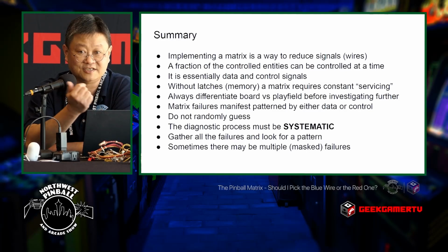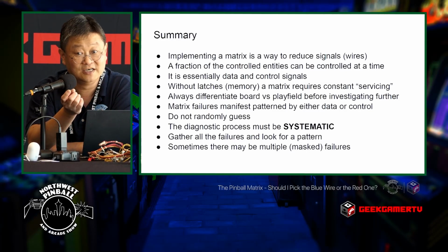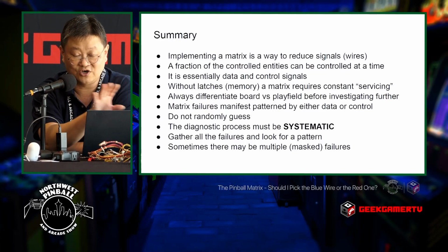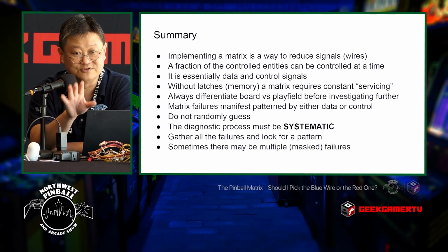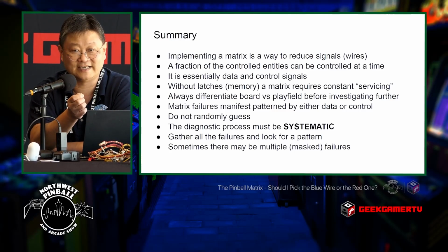Alphanumeric displays are another example of this. If you use a camera, sometimes you can capture images at a certain state where your eye sees a totally seamless display. If you use a video camera, which captures at a certain refresh rate, it will see the strobing nature. Same with a dot matrix. Point your camera, take a video, watch the frames, you'll see it. It's just that your eye can't see the latency because it's slow.